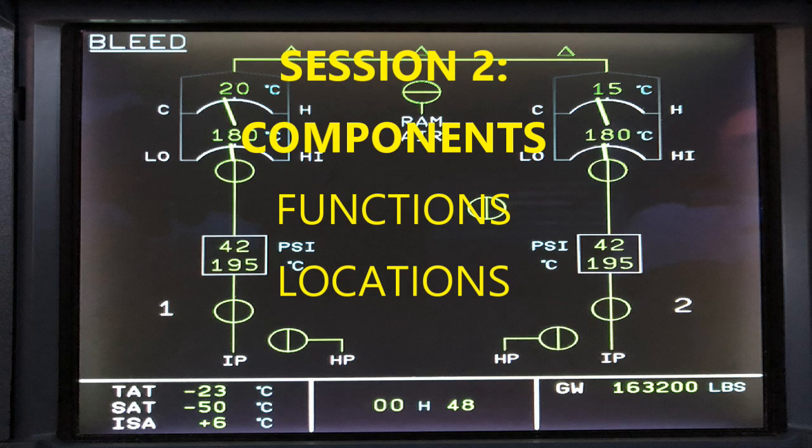We also have, remember I mentioned overpressure, always making sure we don't have an overpressure coming into the user systems from the engines. So we have an overpressure bleed valve that's going to close automatically when the engine bleed air exceeds a certain set pressure, because we don't want too much going to the user systems throughout the aircraft.